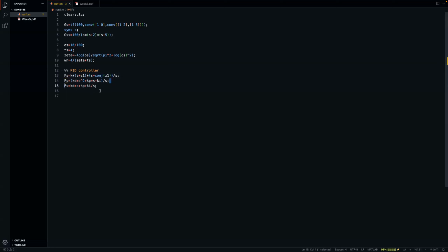But when you use this week's code, when you're designing a PID controller, you would be better off with these two representations here. They are basically the same, but they have advantages over the line 13 definition here, because you are looking at linear coefficients here. And since this is a controller, it will be multiplied with the system. The system has nothing unknown in it. The controller has all the unknowns. So their multiplication will just give you linear unknown coefficient polynomials, sort of.